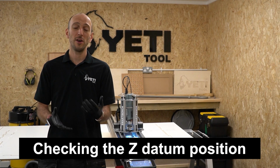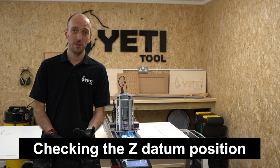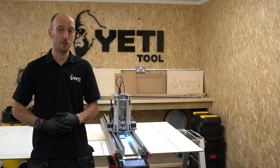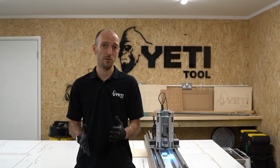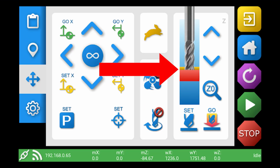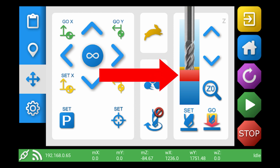Just like with the XY datum, we can visually see how the job's going to look in the Z-axis by looking at the screen. You'll see two color zones, a yellow zone and a red zone. And the Z datum is actually at the point where the yellow zone meets the red zone. Now you might wonder what those different colors mean, and it's pretty simple. The yellow zone is any movement in the Z-axis in the job file which is above the datum, and the red zone is any movement in the job file which is below the datum.